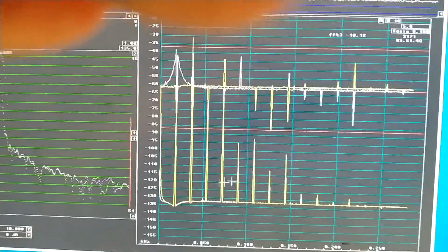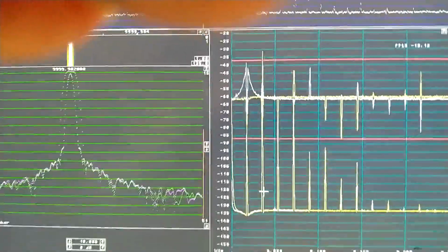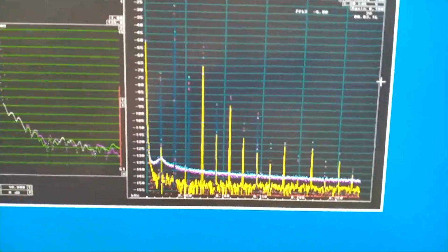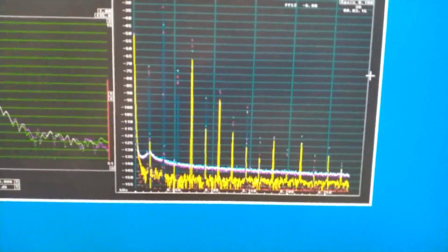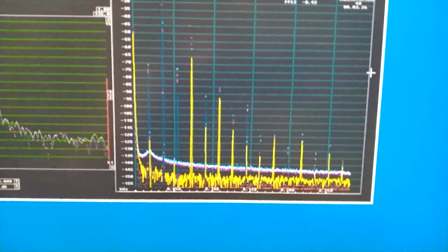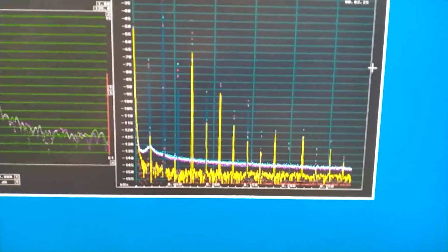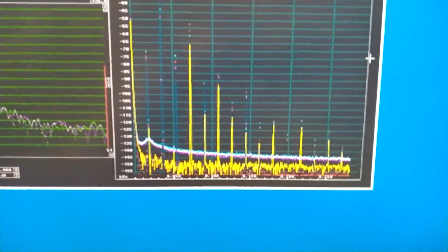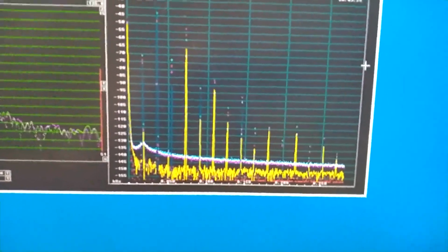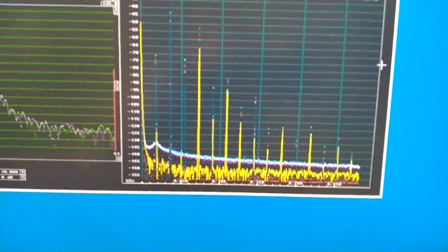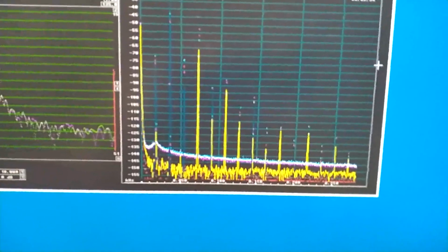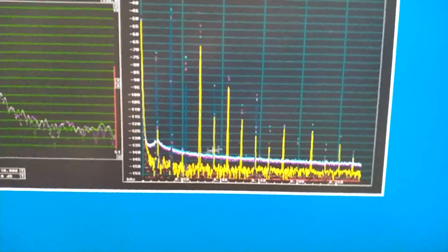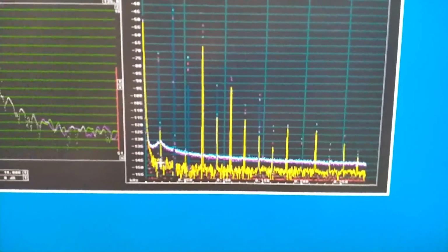And of course, I don't know what is behind this. It's the same setup, but I have reduced the amount of noise that I'm adding. I simply removed one of the series connected amplifiers to reduce the flat noise floor that I'm adding to the Wenzel oscillator. And I will wait again to see what happens with the phenomenon here at close range.